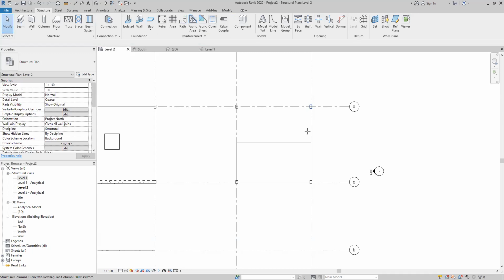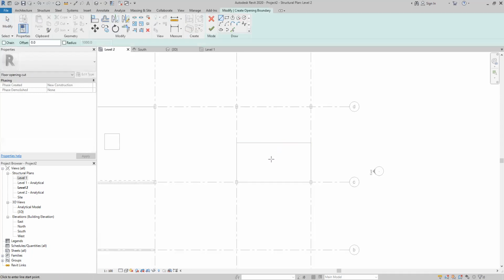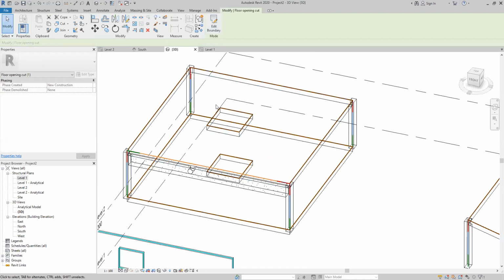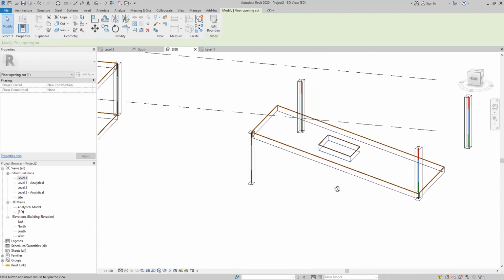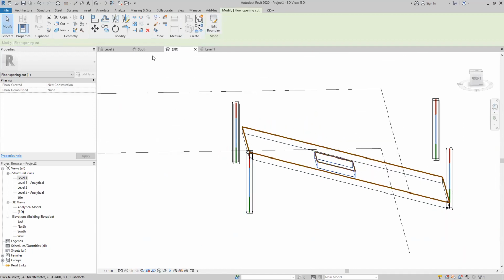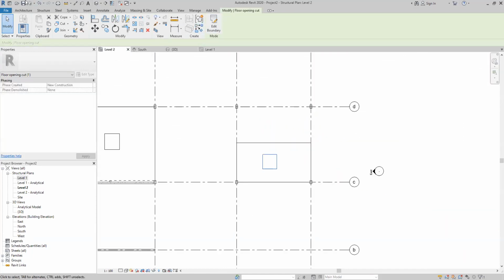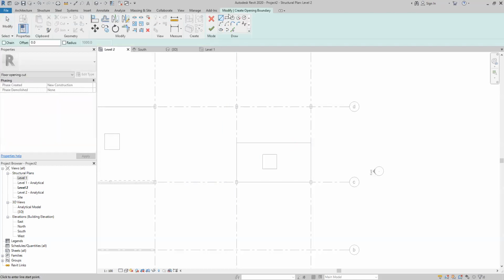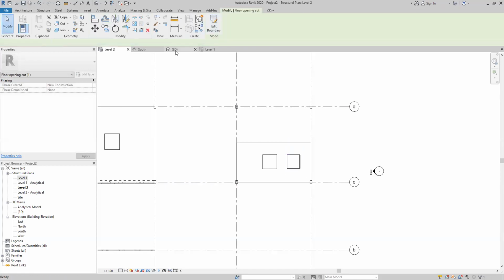now vertical opening, right? So I click the vertical opening, then come under the slab and select the surface, right? Then you can draw your opening. So I draw the rectangular opening now, right? And click OK. Okay, so go to the 3D. Now you can see the opening. Okay, so now look into it, right? The opening is vertical. To understand the difference, I draw another opening using the normal surface option. I select the surface. I am doing the same thing side by side. Click OK. So let's go to the 3D and see the difference.